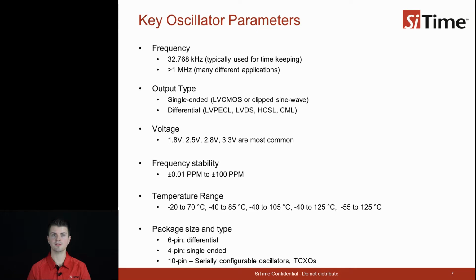For example, 25 megahertz is often used as the reference frequency for 100 and 1000 megabits per second. The allowed frequency range would be 25 megahertz plus or minus 100 parts per million. This equals 25 megahertz times 1 plus or minus 100 divided by 10 to the sixth.